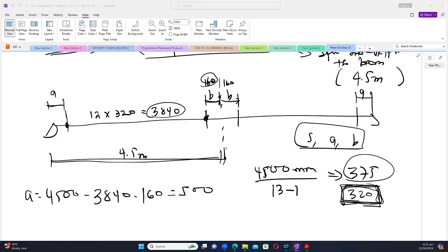Yeah, that's what we have. That will govern because that's where we don't want the slip to occur. So technically, that interface becomes our neutral axis. Because if the slip will occur at that point, then we don't want it to slip at that point at all. So we consider the force for concrete, which is the one above that interface.